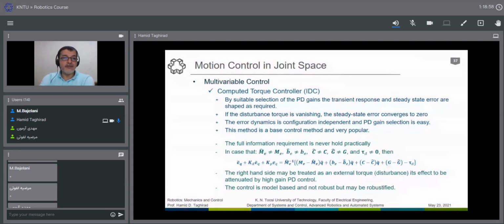If, for example, your Coulomb friction is 1 Newton, and you take 2 Newton out of that, if you overcompensate, then you make a very nice stable system go to instability, and this is not good. So these two are the points that you should think about. You can compensate for that, but don't use the full knowledge. Use the minimum values that you have calibrated everywhere to make sure that the remaining part is stable.